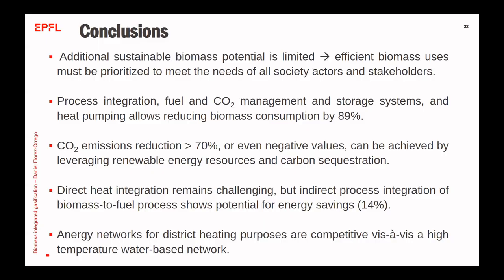We know that the district heating network should use only low-grade waste heat because the needs are at very low temperature. Then also the utilization of heat pumps and partial electrification may help reduce the consumption of biomass and then prioritize the biomass for other uses in the industry.